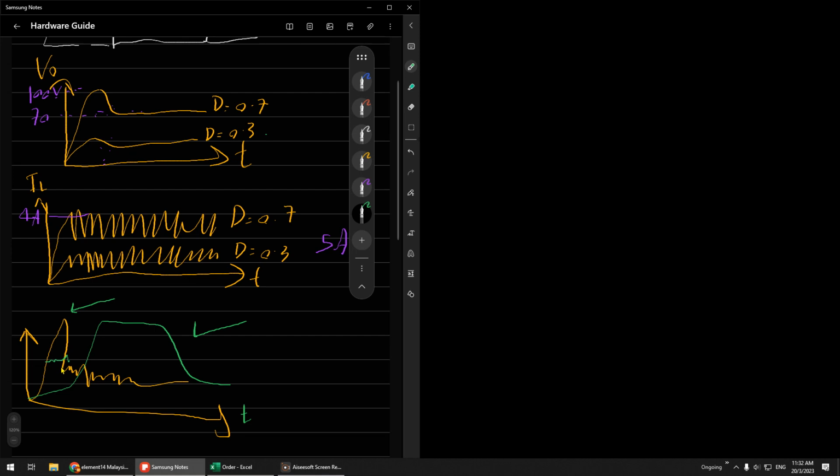The wire can handle it usually, but if it is more than 10 millisecond, for example for a motor it can be around 3 second, 4 second, you have to consider this current. You have to consider maybe the steady state is also the same, 4 ampere. Maybe this one is 8 ampere, and this one also 8 ampere. This one you don't need to consider, you just set it to 4. But for very long transient, you have to consider the 8 ampere.